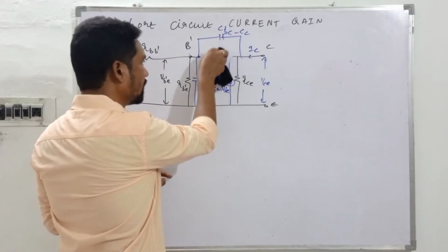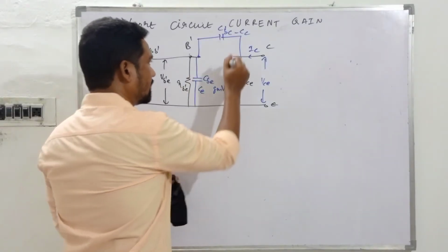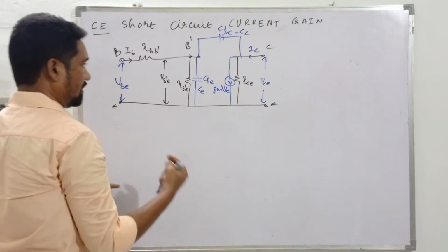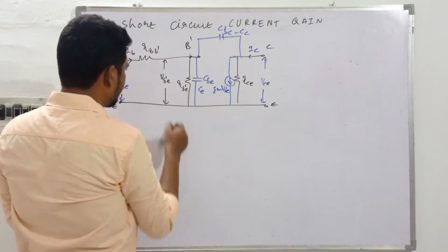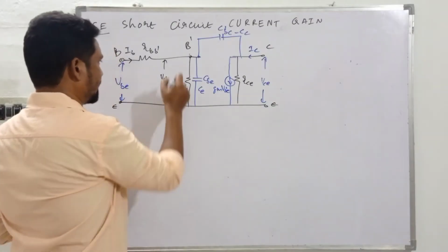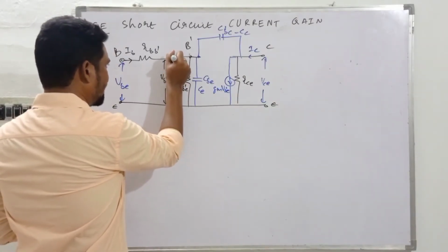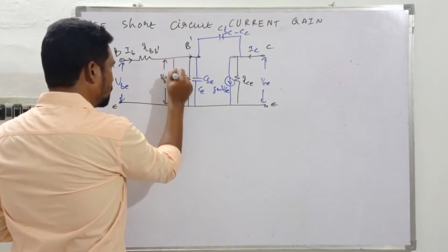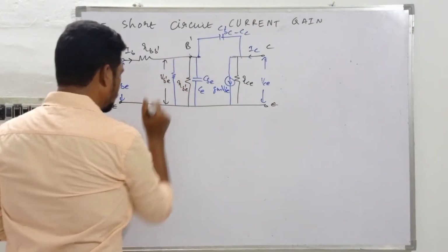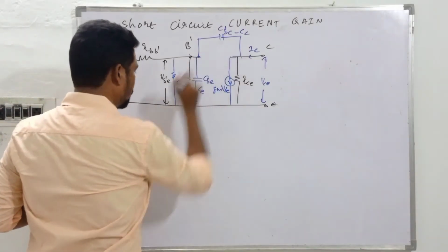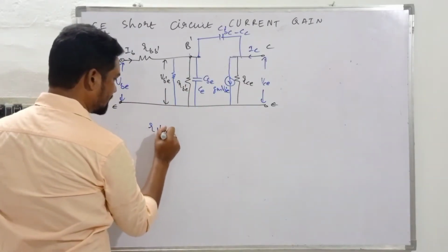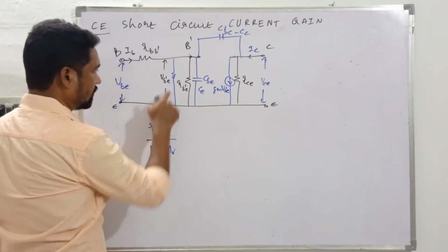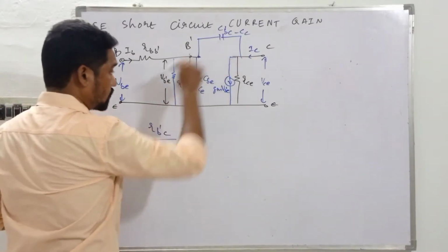According to Miller's theorem, I have started applying Miller's theorem. Why? Because I need to go further with the analysis, and I want to make the analysis simpler. So what amount of resistance should be placed over here? I need to place a resistance here. It would be better if I go with another color. What amount should it be? That resistance was RB'C, isn't it? RB'C by 1 minus AV is what I need to plug in over here, if I remove this one.